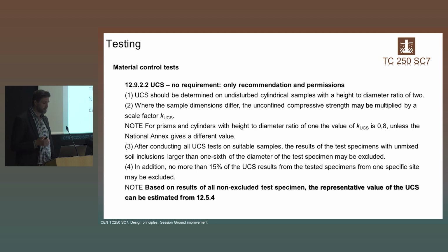This is a current practice to test a height to diameter ratio of 2 for concrete before soil mixing, for example, to have more tests to be interpreted, taking into account the variability of the material. For example, we commonly use a ratio of 1 in a lot of different countries. And thus, you may apply a 0.8 if you want, adapted to your national practice, because that takes also the other factor, the N samples, the other factorization factor of 0.7 that you have in the code. Thus, you may apply that, but that's not mandatory.